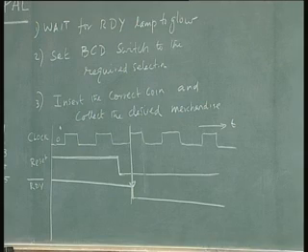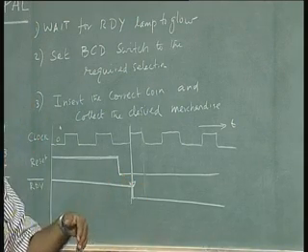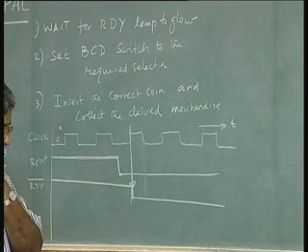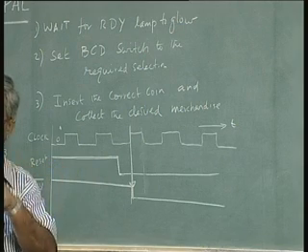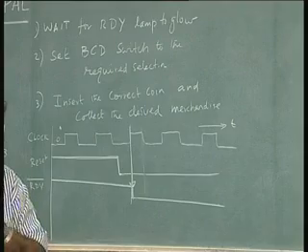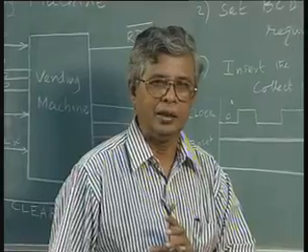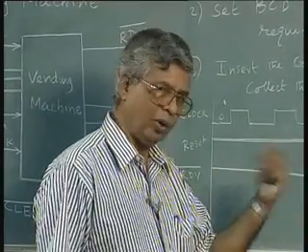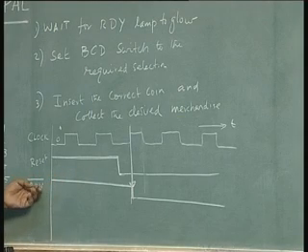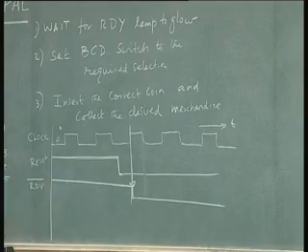We can have an LED connected to glow when the voltage is high, or you can have an LED connected to glow when the voltage is low. You might have seen this in your earlier circuits, earlier course in digital design. We can make an LED on for 1 and off for 0, or you can make an LED on for 0 and off for 1 by connecting the anode and cathode with proper polarities. So, in this case we are choosing RDY to be low. When the signal is low, the LED will go on. So, this lamp will glow.